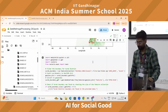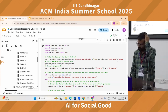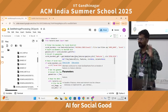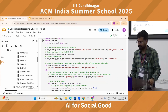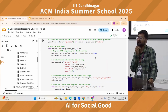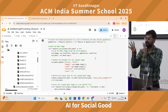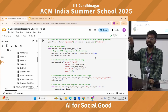Correct. So here the FAO boundaries are available, and I selected Surat from Google Earth Engine, and all the NDVI images I already have in this cell. So I just overlaid Surat over here. And one more thing I did is that since my area of interest, or ROI, is just the Surat district, I don't want to keep the dataset outside the Surat boundary. So that operation is called clipping of a raster image based on some geometry.